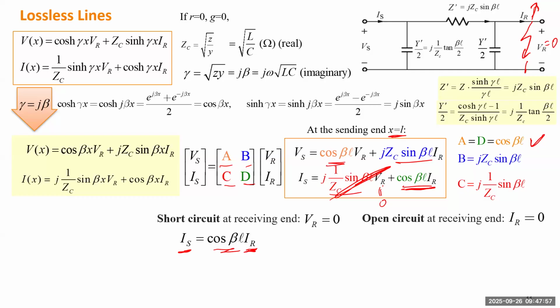Another fault is the open circuit. If we open the circuit, we make the load current 0. That seems fine, right? Because it doesn't introduce high current to the system. But the impact will be on the load side, because we want to know how much this voltage can change. We want to maintain this voltage within the operating region, such as maybe 5% around the nominal value.